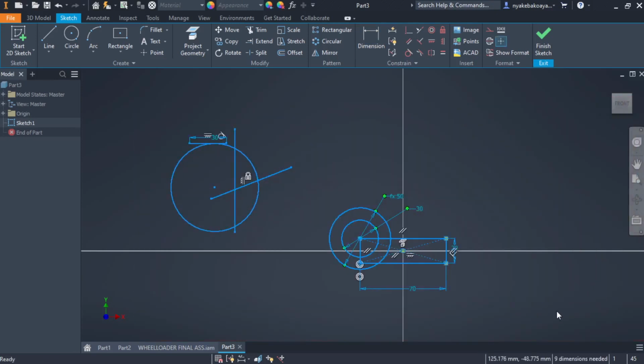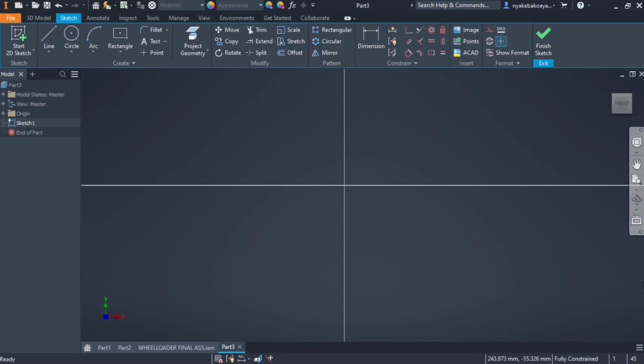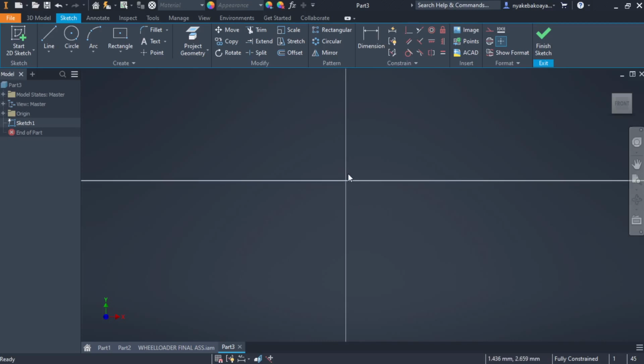Let me erase everything here, click delete. By deleting, there's a problem here. The problem is now we don't have our reference point here. I did that knowingly because sometimes you encounter these issues and then you don't know what to do. Because if you try to draw a line and you hover the cursor here, you see it doesn't turn greenish, because it doesn't have a point where it snaps to. Now if you encounter that problem, you can undo, but what I like doing is this.